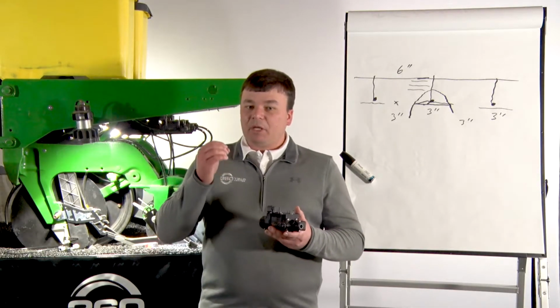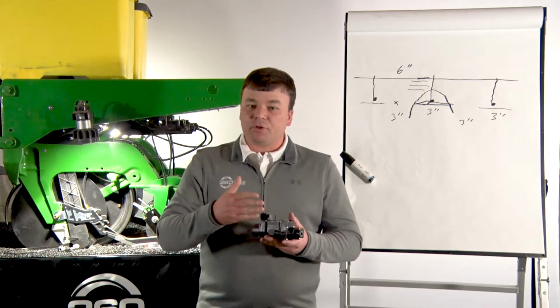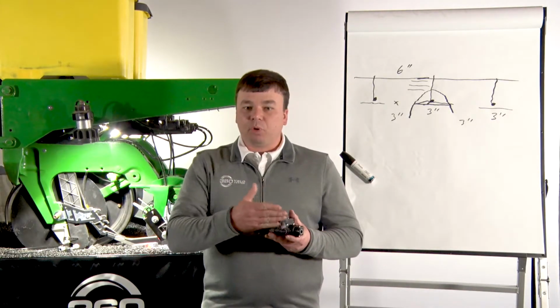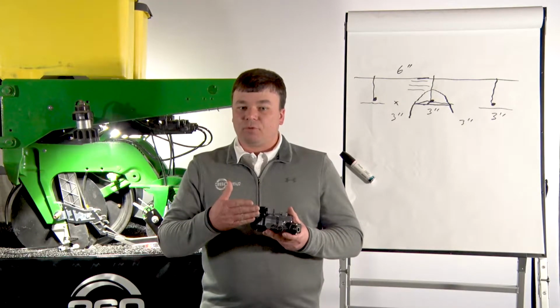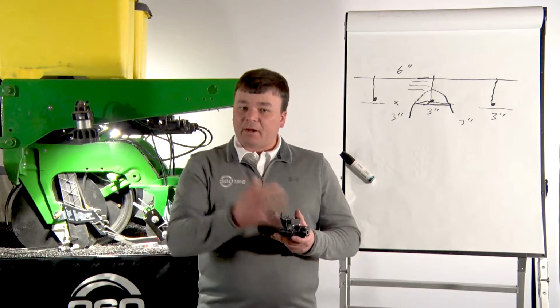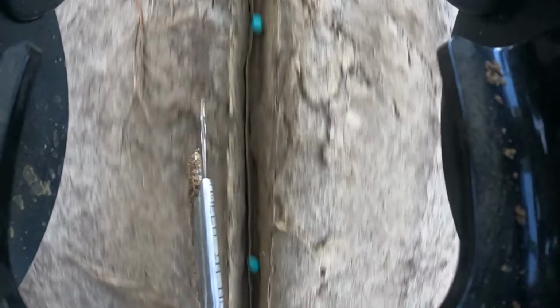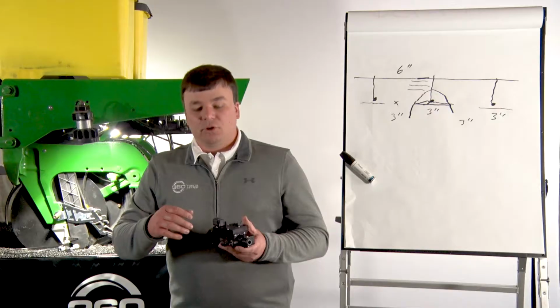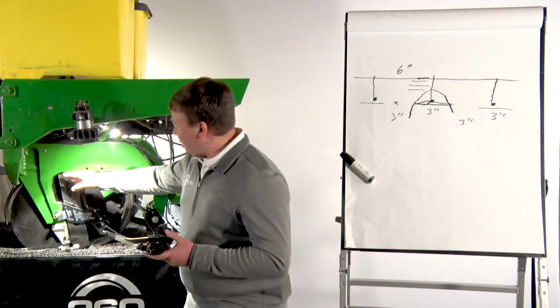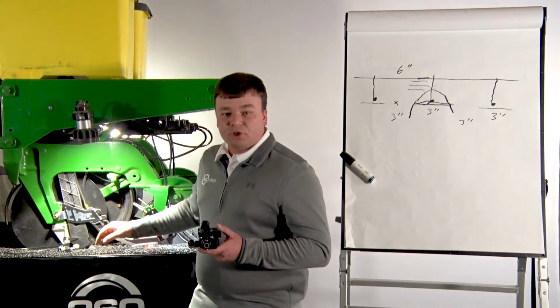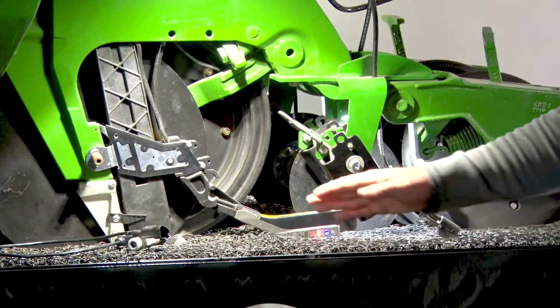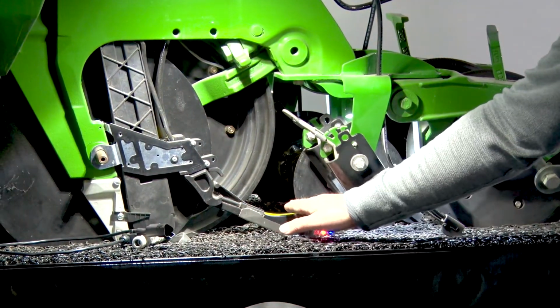And then our 360 Dash valve takes over. And based on that timing, it opens up the valve, and it's a plunger, it's a needle valve that we can pull back different amounts to change the rate, and then quickly open and close to be able to create nice consistent dashes with a clean start and a clean stop. So as the Dash valve now knows the seed is coming, it works its way down, comes to its home position. As we're then counting the time, we continue to count based on the attachment you're using.